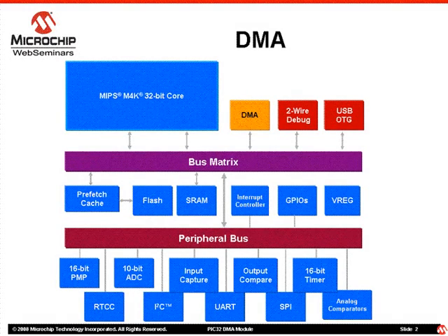The PIC32 DMA module is designed to increase the data throughput of PIC32 based embedded systems. In addition to standard data movement modes, the PIC32 DMA module includes integrated programmable CRC engine, channel chaining, and pattern matching modes to further reduce the CPU burden and increase overall system performance.